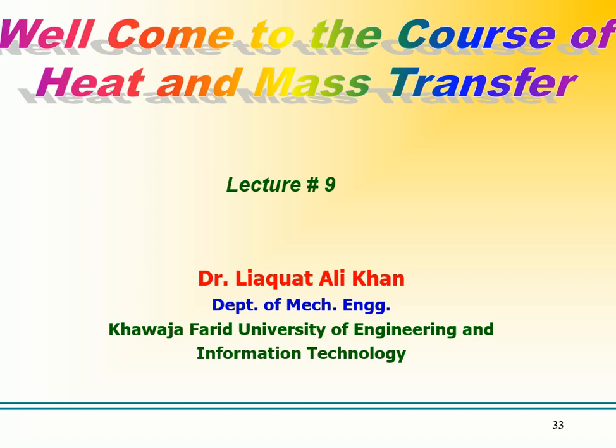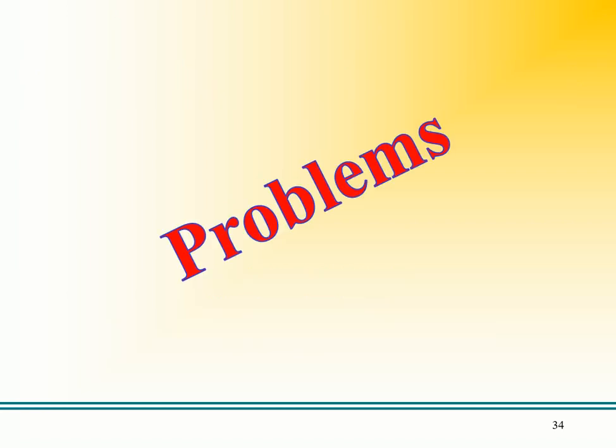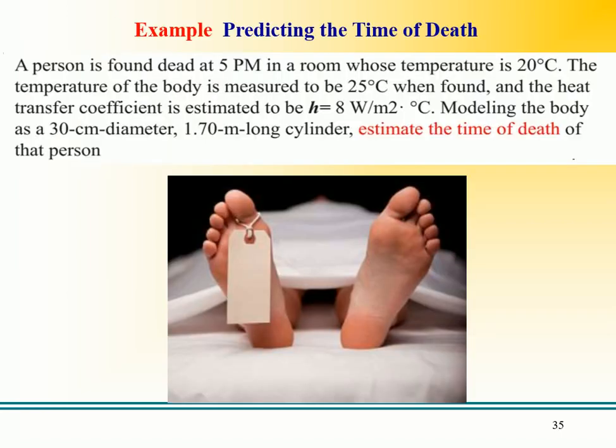Dear students, today we solve, inshallah, the problem regarding transient conduction. In the previous lecture I gave you the theory about transient conduction, and where the lumped capacitance model can be applied: where the Biot number is less than 0.1, and of course, the temperature gradient within the solid body is negligible. So let's solve the problems.